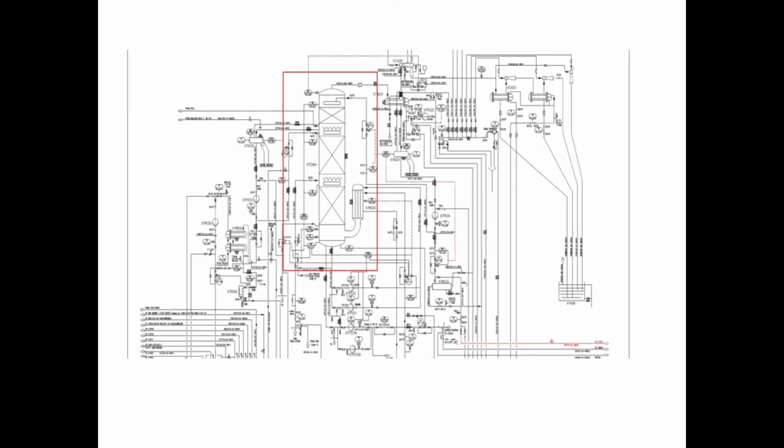There are a lot of major equipment that can be found in a fractionation process. One of the major equipment is distillation column X7C004. Based on the P&ID shown, the red color box indicates distillation column X7C004. The feed of this distillation column is from the outlet stream of X7C002, which is a mixture of fatty alcohol composition.